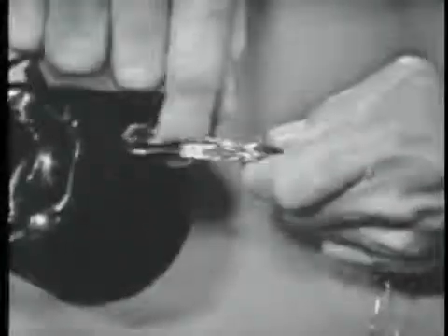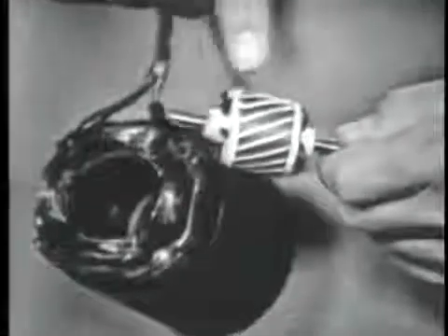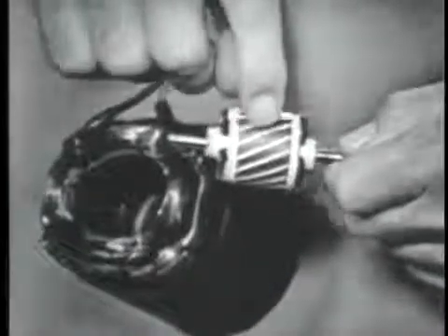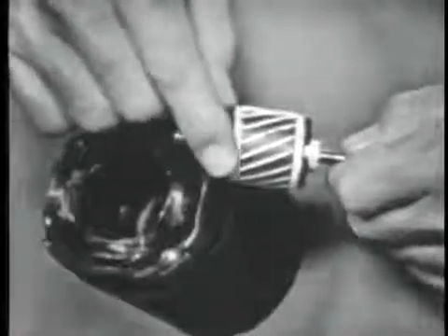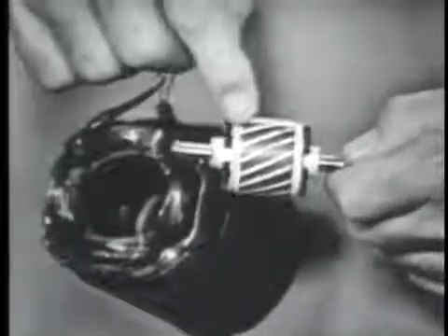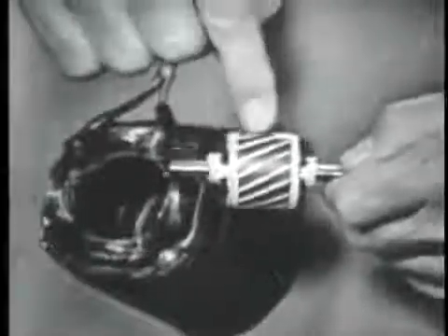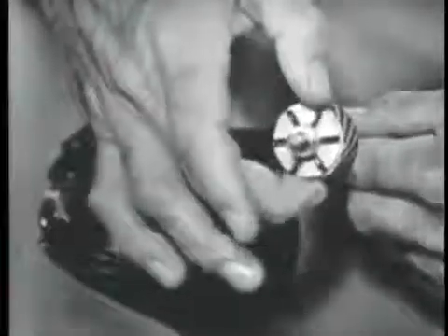An electromagnet, right. Now actually, the rotor is the same thing, or almost the same thing. And a rotor is made in a very, very similar way. Instead of using windings of wire, however, we use a conducting ring on this end, a conducting ring on this end, and they're joined together by conducting bars, these little white lines. And the reason I say conducting, sometimes they're made of copper, sometimes aluminum. This one happens to be aluminum. Now, as the rotating field goes around this rotor, current is caused to flow in the rotor, which sets up a magnetic field, and the rotor develops a north and a south pole.